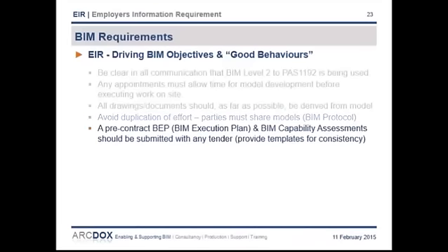If you've taken the time and trouble to write an EIR, then you should make sure that anyone tendering on the project for either design or construction services submits the pre-contract BIM execution plan and capability assessment with their tender to firstly demonstrate that they've bothered to read the EIR, but also to show how they're going to fulfill the requirements. As mentioned earlier, it helps if you provide a template for people to complete for consistency to make comparing and assessing these easier.